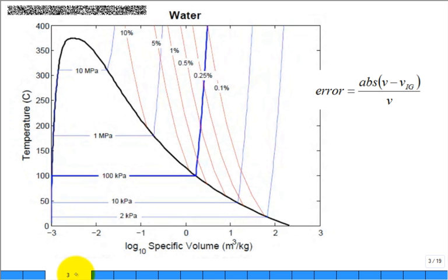And then you can do this repeatedly and plot it on a temperature-volume diagram. Because the specific volume ranges over such a large range, we plot it on a log scale. This is our traditional dome. Out here are the states of saturated vapor, true? Along that line. Out here we would definitely agree that it behaves as an ideal gas, way far away from the dome.